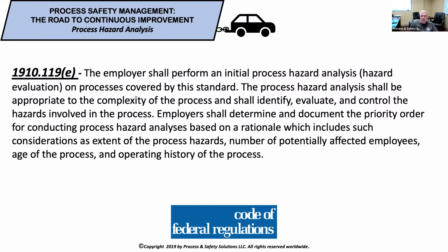This last sentence really has to do with when the PSM standard was initially promulgated. Facilities had so long to conduct their initial PHA, or process hazards analysis, of each of their facilities, and they had to be prioritized based on the criteria held in this last sentence.